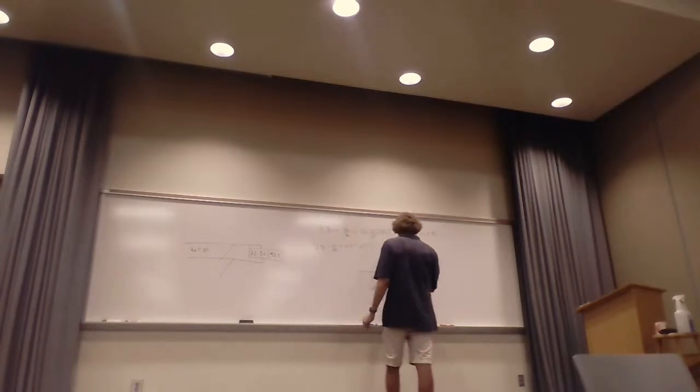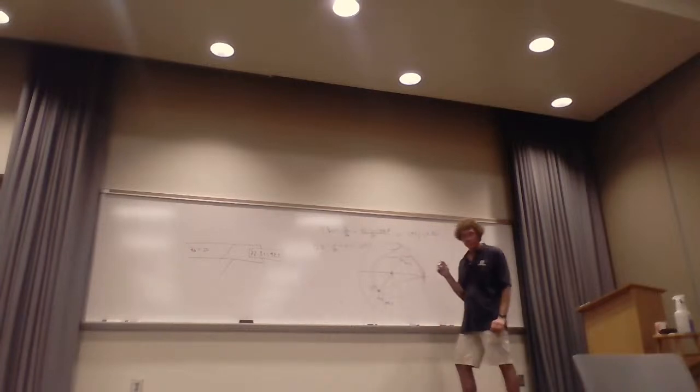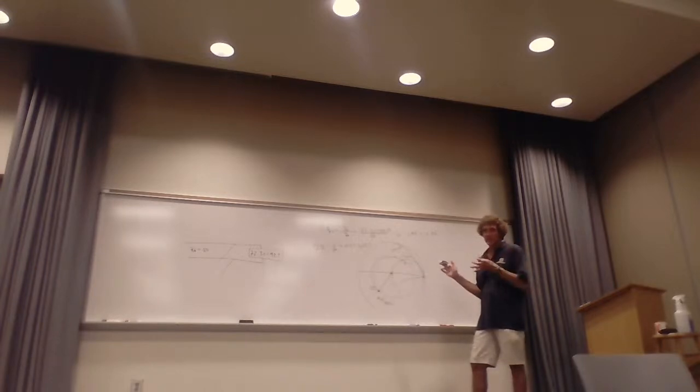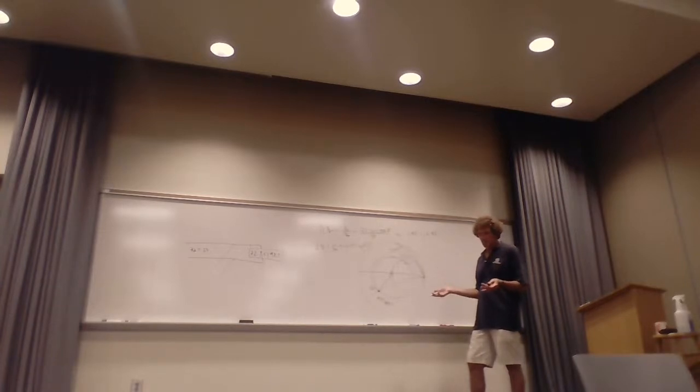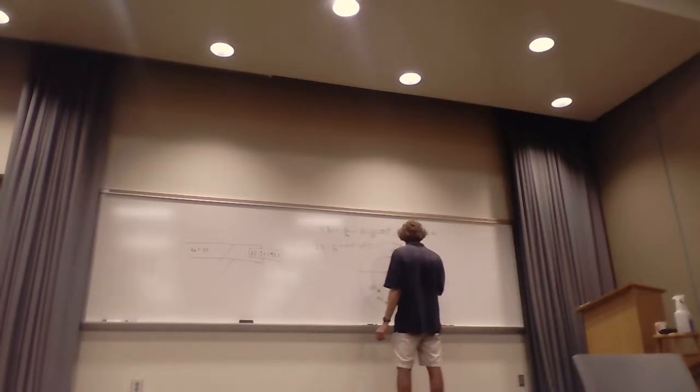Now, there are 2 points that I can end up at. The first is right here, and that's going to be 1 plus j something, right? Because you want to intersect the 1 circle. Once we get rid of that imaginary part, it's over, because when we denormalize it and multiply it by the characteristic impedance, we're looking into Z0. Then the reflection coefficient is 0. But there's also a point down here at the conjugate point, which is 1 minus j something.